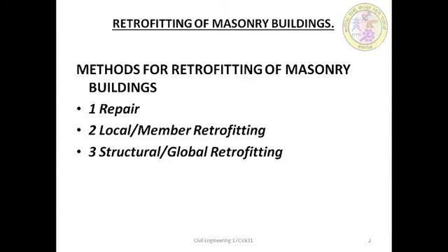Whatever the different methods there are for the retrofitting of masonry, the choice of a suitable method depends upon the structural scheme and the employed building materials, along with a feasible and economical technology. Moreover, an understanding of failure modes and structural behavior, with the weak and strong aspects of design derived from the earthquake damage survey, also influences the selection of the retrofitting schemes.